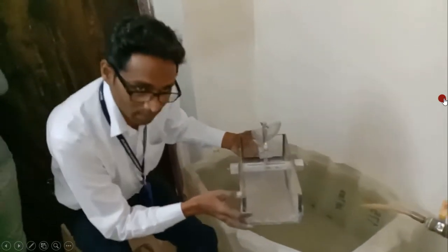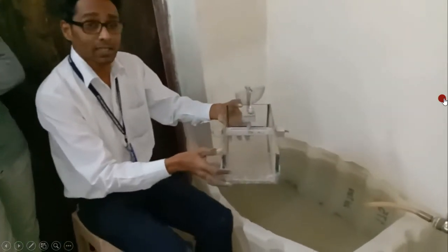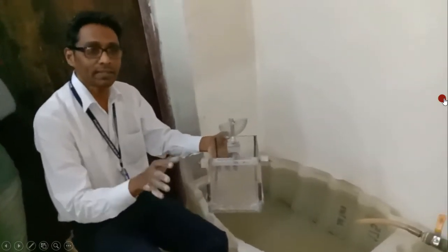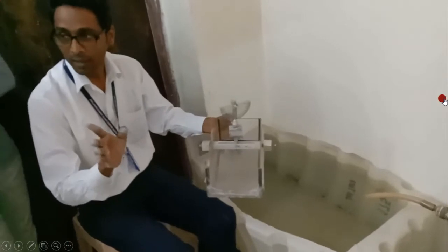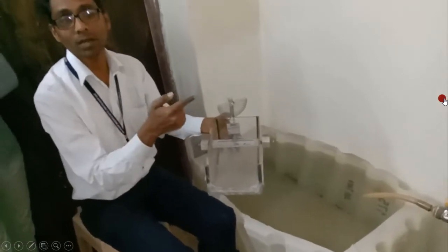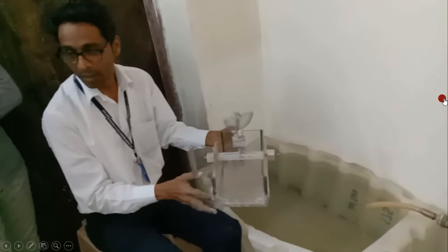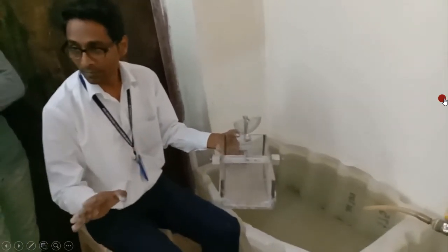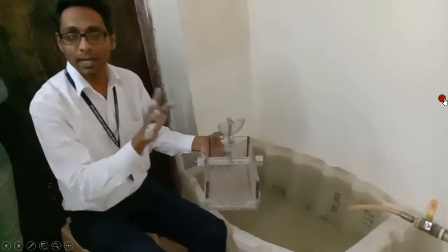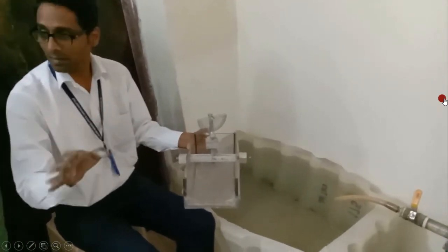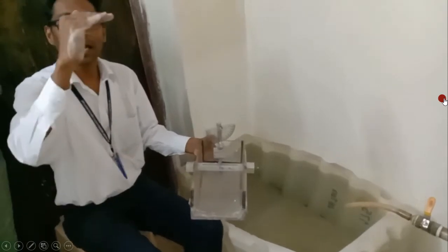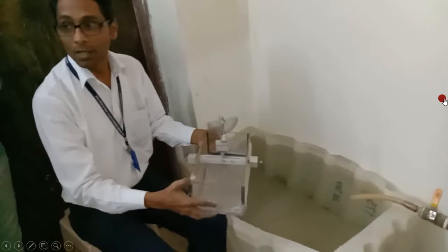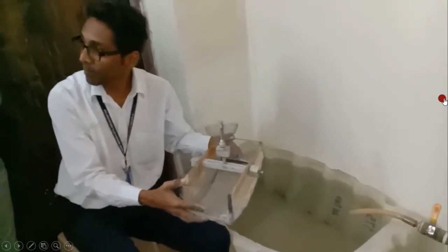After the manufacturing, we obtain the metacentric height. If this metacentric height comes negative, in that case point M goes below G, and we say that the body is not stable. When the metacentric height comes positive, point M lies above G, and in that case we say that the ship is stable. So this is done experimentally.